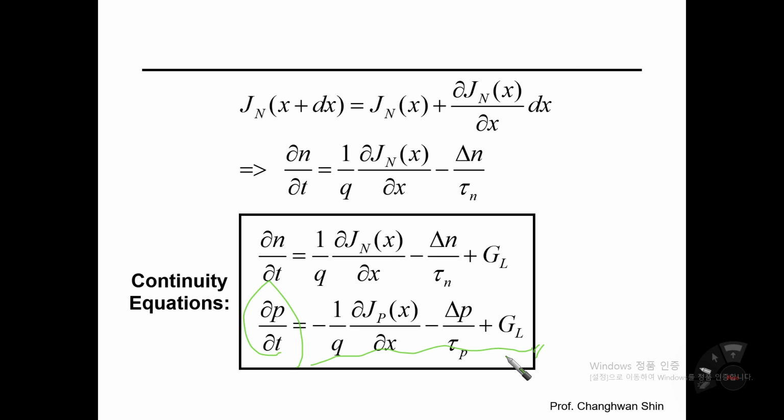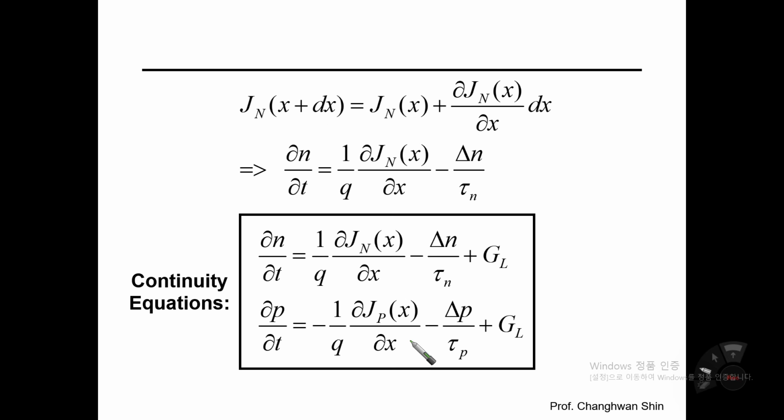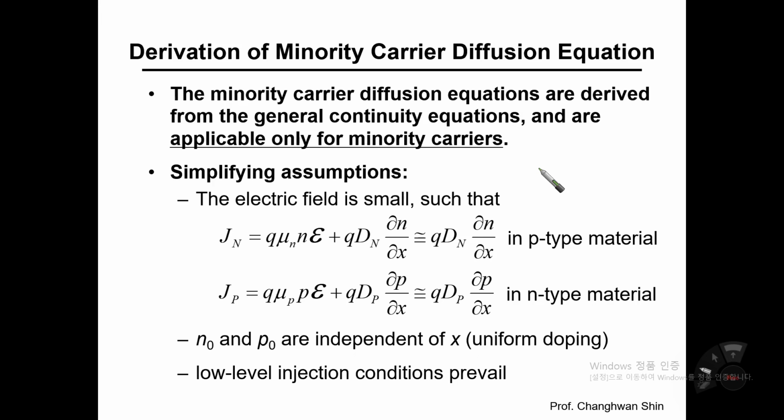However, this equation is still very complicated, and the reason we are studying the continuity equation is to have a deep understanding of how the holes in the n-type material are moving, especially for the PN junction diode in the end.